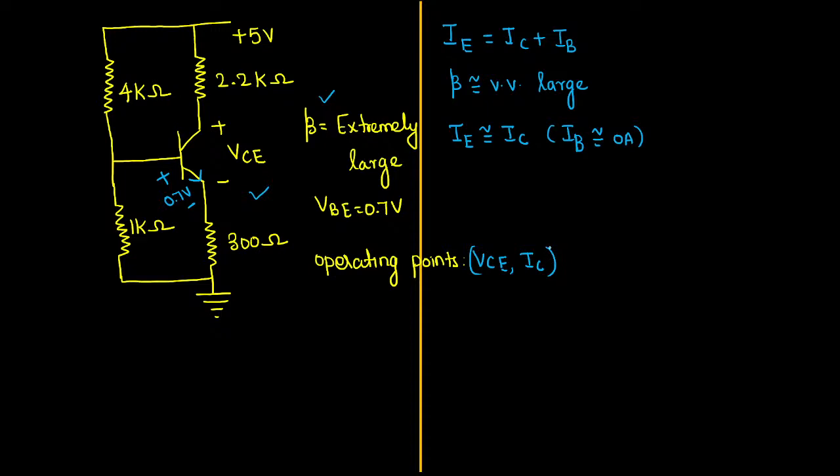Fine, sir. There is no direct clue, and I have also told you that whenever you observe two resistors at the base junction, and a single resistor is not directly connected to your base terminal, then apply Thevenin's theorem to the circuit. How will you Thevenize? We have to treat the entire transistor as a load according to Thevenin's theorem. Then you can draw the circuit like this.